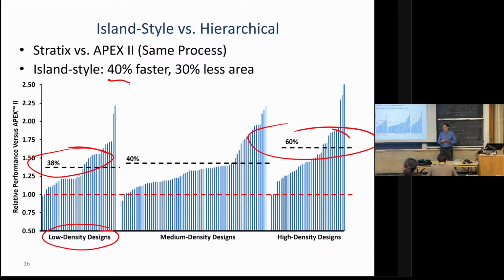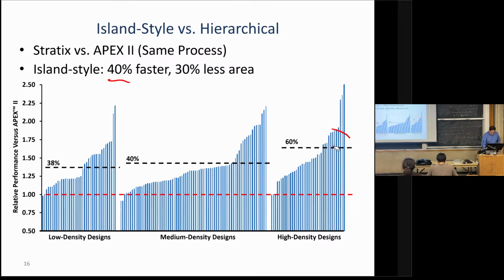So if you multiply, the area delay, this is twice as good, which is a big improvement. Cutting the area delay product in half basically makes the chip twice as efficient. So that's a very big improvement. So it's a demonstration that at least for big designs, going hierarchical all the way just is not as efficient as island style, because that's the biggest single difference between these things.